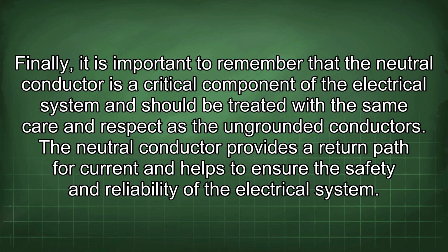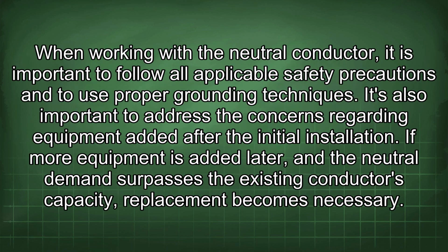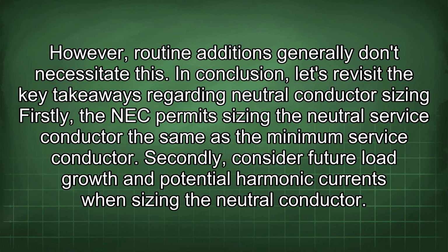and should be treated with the same care and respect as the ungrounded conductors. The neutral conductor provides a return path for current and helps to ensure the safety and reliability of the electrical system. When working with the neutral conductor, it is important to follow all applicable safety precautions and to use proper grounding techniques. It's also important to address the concerns regarding equipment added after the initial installation. If more equipment is added later and the neutral demand surpasses the existing conductor's capacity, replacement becomes necessary. However, routine additions generally don't necessitate this.